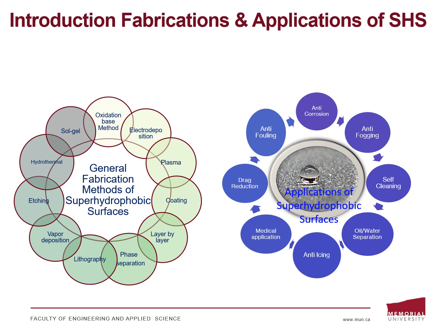The superhydrophobic coating results from a combination of the hydrophobicity of the surface material, chemically hydrophobic, and surface topography, physically rough. The superhydrophobic coating became commercially available in 2016 and opened the doors to a wide range of applications such as self-cleaning, anti-fogging, anti-corrosion, anti-fouling, anti-icing, oil-water separation, and some medical applications, but our focus will be on drag reduction.